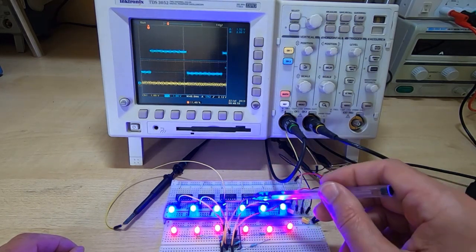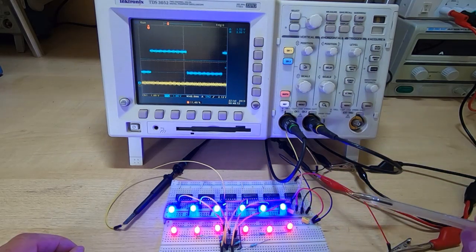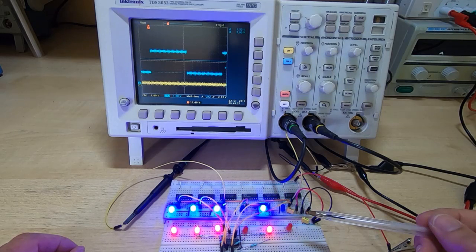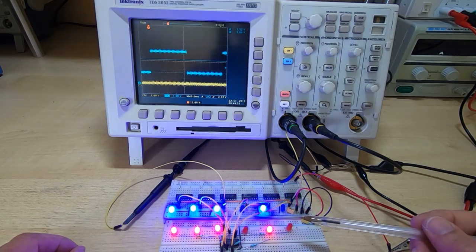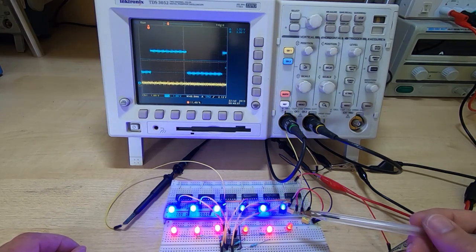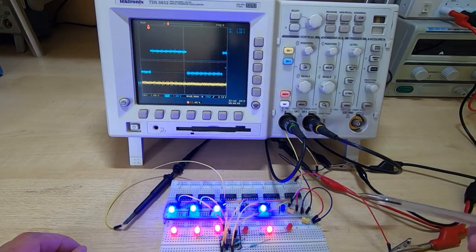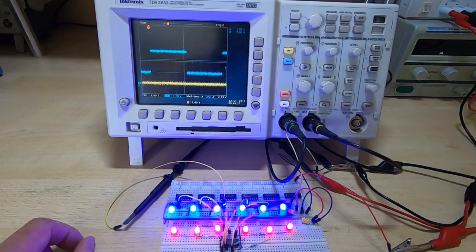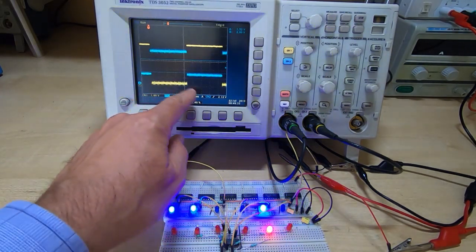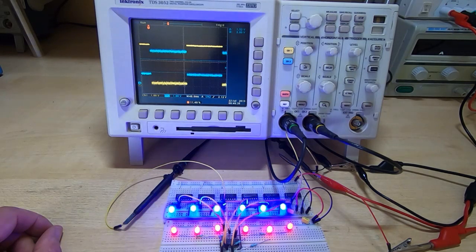So if I was to start unplugging the different device types, you'd find that the behavior of this circuit would completely change, because the input value being fed to the individual devices is going to be different based on the loading that each input is seeing. So I'll reduce the swing back down to 0.7 volts, and you can see straight away that we've recovered some of the units. The 7414 Schmitt version is now not apparently working.